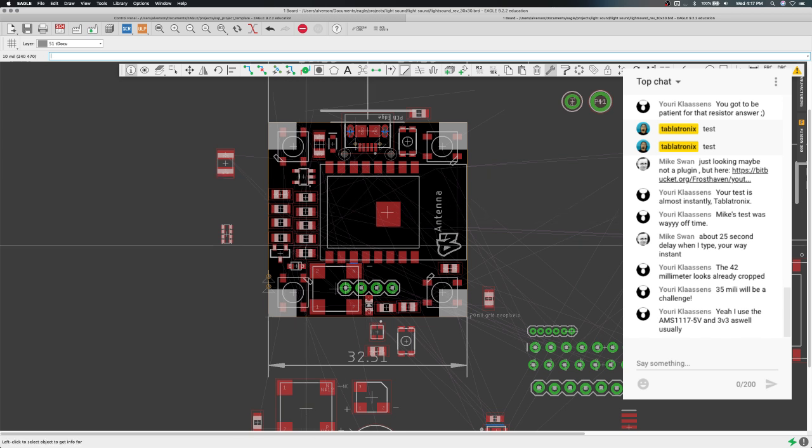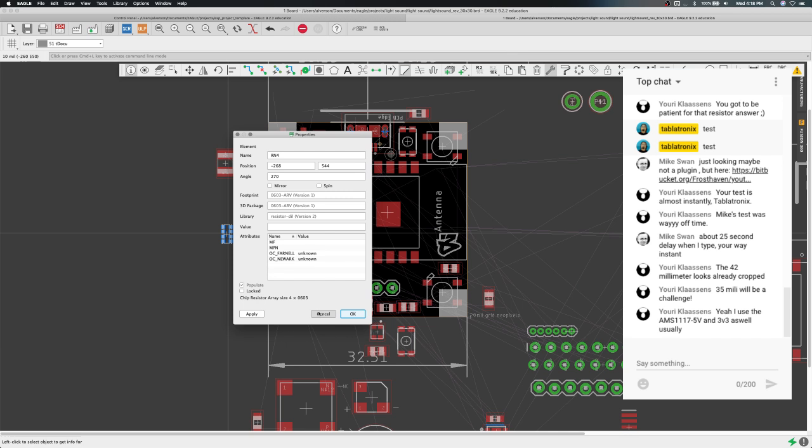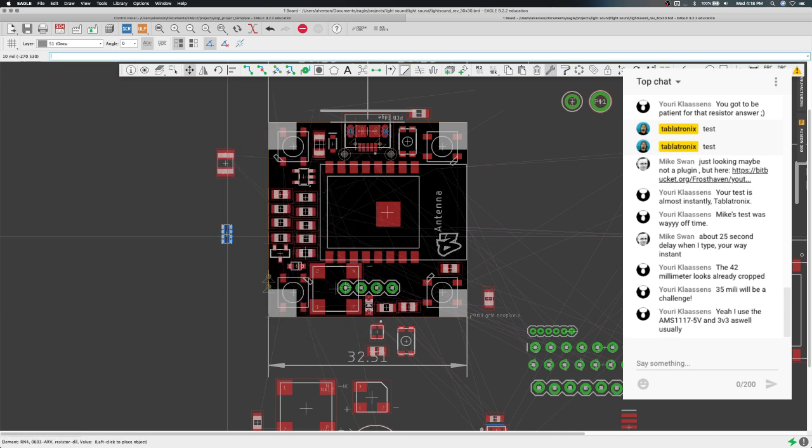Another problem is you have to have four pull-up resistors for the ESP. So I thought, well, maybe I could put one of these little tiny resistor arrays on there. Look how big that little tiny resistor array is. There's four 10K resistors, but I thought I wanted to kind of keep this hand solderable, maybe, if I can. That would be cool, because then you can sell it as a kit or a board, plain boards. And everything but the USB connector should be hand solderable mostly. I've done rework on almost most of these components, and they all are pretty easy.